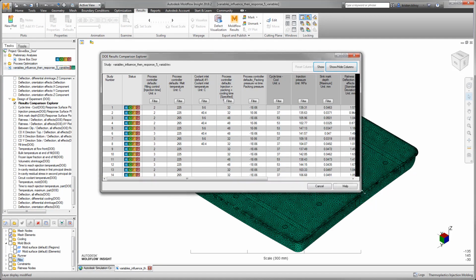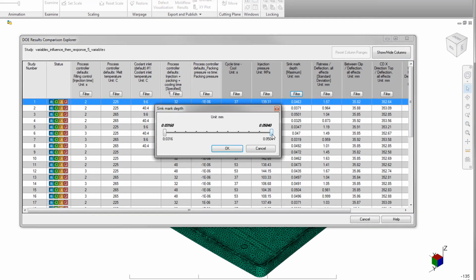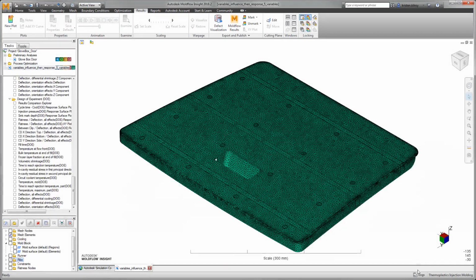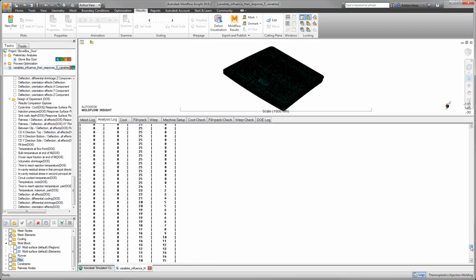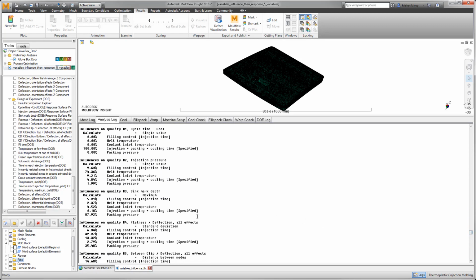options to only those with acceptable sink mark depths. It also shows the other quality criteria for a high-level look at how those are influenced by the process settings chosen for the reduced sink mark depth. Further details on the ranking of the influence of each variable in the DOE can be found within the log. In this example, notice how it indicates pack pressure is the highest.